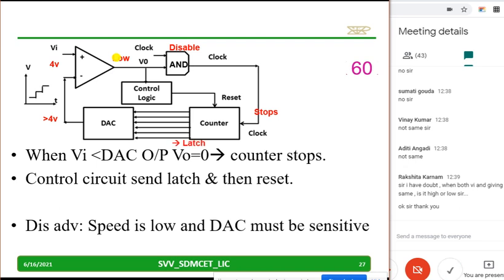It's a block diagram; some of the information we may not be putting. And it will send a stop, a reset, to the counter. Take the second stop as a reset to the counter, and try to copy this down and understand. It's very simple. So we have discussed the first one. It is also the same, but there the ramp was linear. Now it is stepwise, changing like that. The remaining operation is almost the same. This is a reset; you copy down.